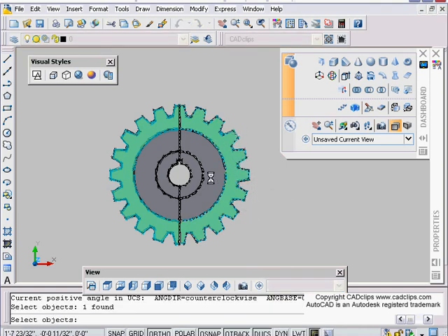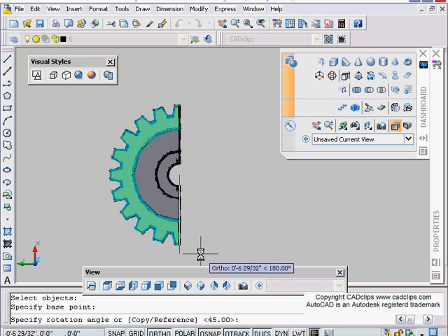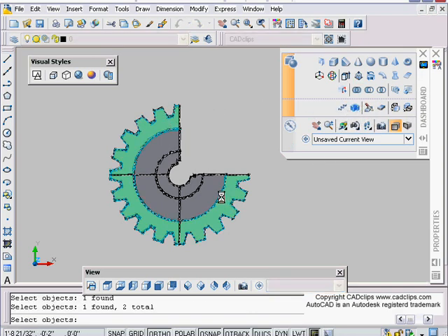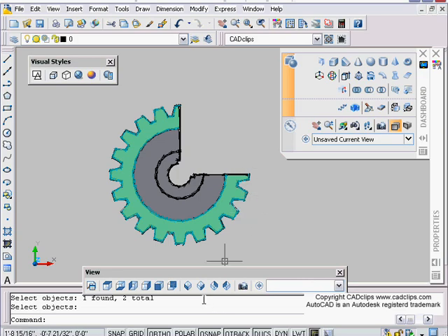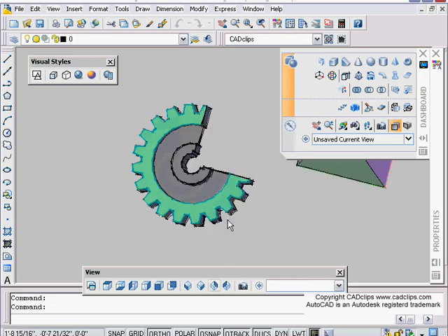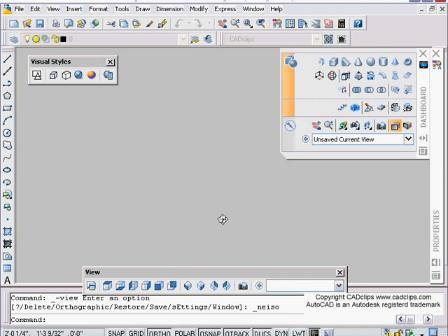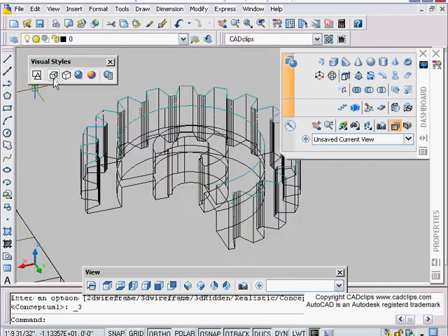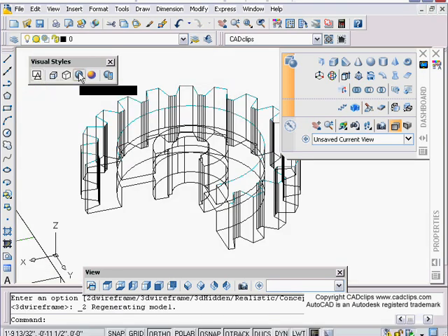Now I'm going to get tricky and rotate this one about this by, you know, this much for 90 degrees, and then I'm going to union these two pieces back together, and then I've got my quarter section that way. So that's how I achieve that myself.